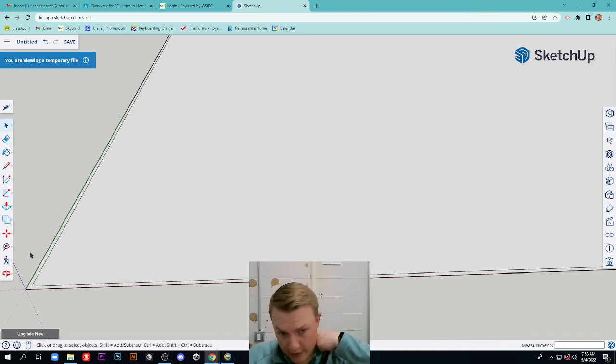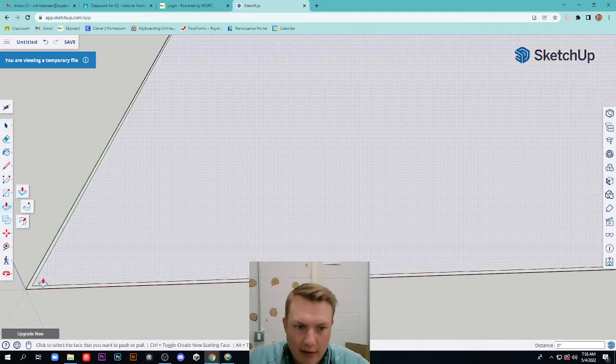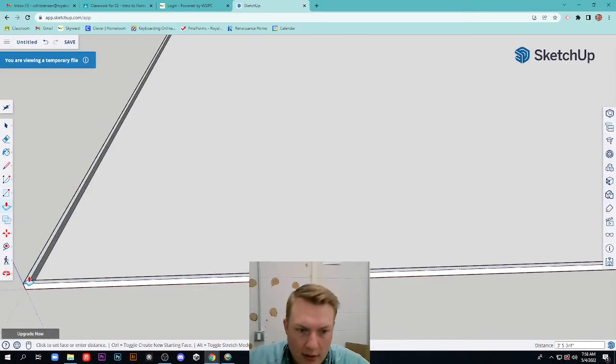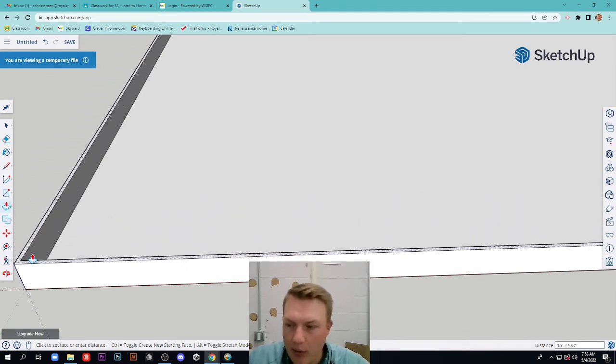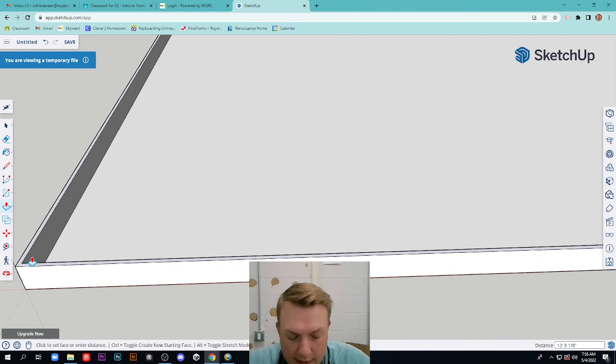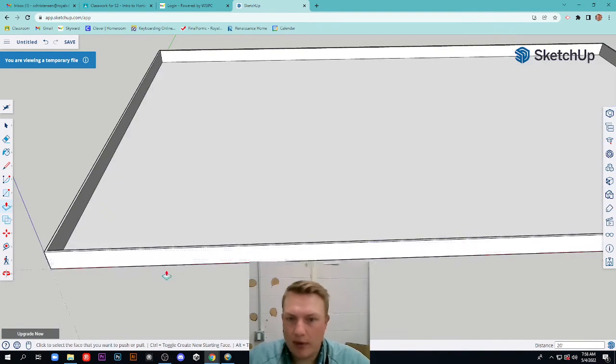Now, obviously, right now this is 2-dimensional. I want it to be 3-dimensional, so I'm going to use what's called the push-pull tool right here. I'm going to click that, and click on my wall here, and you can see I can start to raise it up. Now, how high do I want it? On a big superstore like this, we're not going to put a roof on the 3D model so I can see everything inside. So I think 20 feet is pretty good. That should be sufficient there.